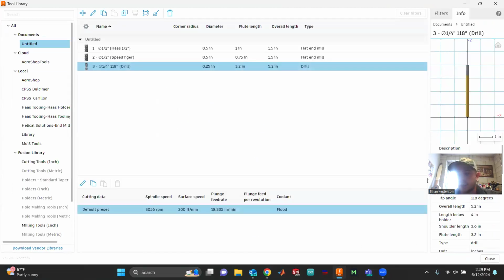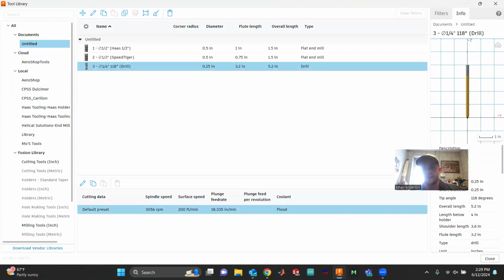Okay, so that should just about give you guys enough info to do speeds and feeds for end mills and drills, and maybe I'll do face mills another time. Generally what you can do is keep surface speeds similar. So, run a 1200 surface speed on your face mill at maybe 5 thou per tooth. Your face mills generally can go up to like 15 thou per tooth and a bit higher, but yeah, okay.